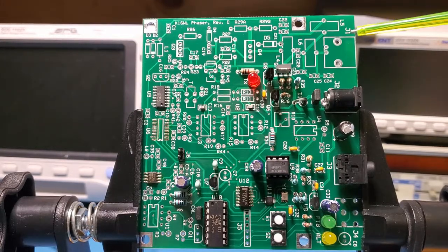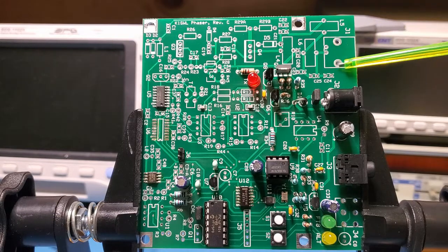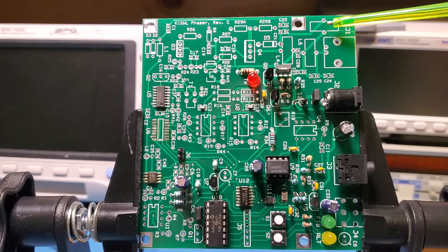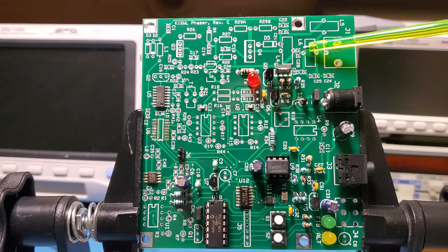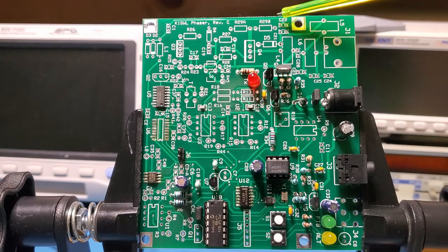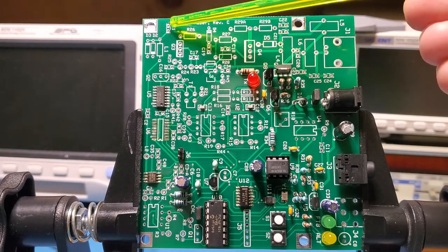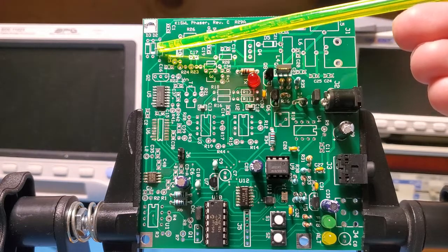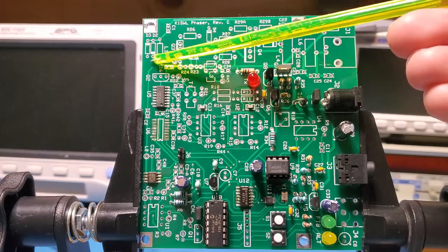Obviously unpopulated at the moment, but here's the BNC jack on the input here. Here's the low pass filter right here. There's the L5 and L6, two inductors on that, and we've got some associated capacitors there. Then the signal runs down this path, through this capacitor, and here are those two clipping diodes I mentioned.